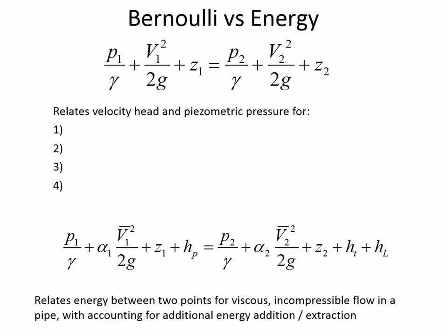So that's why the pump head term is on the left side of that equation, is because we're adding the amount of energy that's added by the pump to the amount of energy that was at point 1 as the water's flowing towards 2. But as it flows towards 2, the amount of energy that remains once it gets to location 2 is reduced by 2 things. If there's a turbine extracting energy, a turbine generates electricity, or if there are losses, meaning the energy losses due to pipe friction and so on. So it really accounts for everything we need it to.